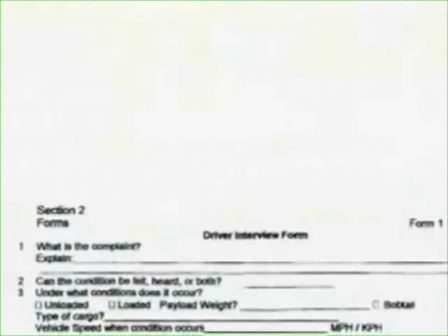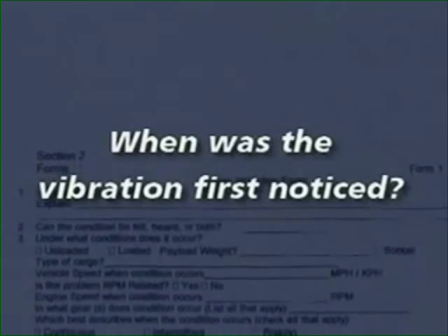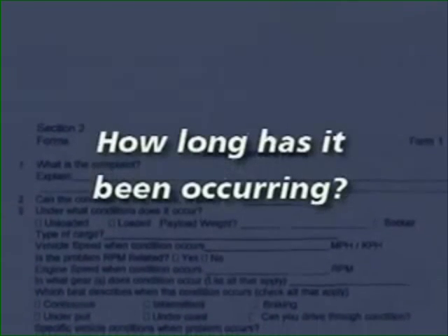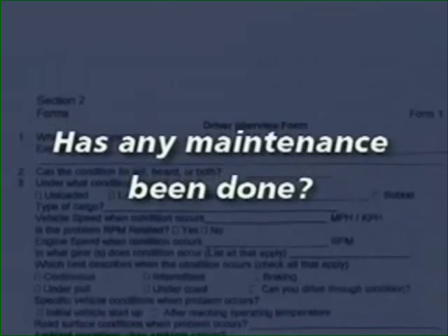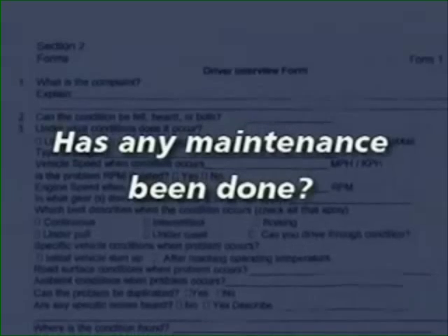In the driver interview, several questions need to be asked. When was the vibration first noticed, and how long has this been occurring? Is this occurring on a new vehicle or a vehicle in which some maintenance procedure has just been performed?